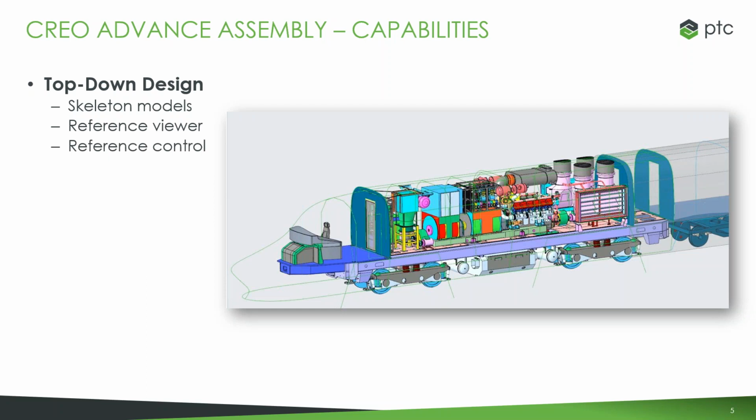So you're able to define best practices to manage or limit the assembly component references. The fewer references that you have, the better, because it allows you to be more flexible, right? So that's where that skeleton model comes in, and you're able to enforce the component references. So what are you going to attach your parts to? We need to be really logical about what everything references so that we can keep our assemblies the most flexible over time and the most flexible for changes.